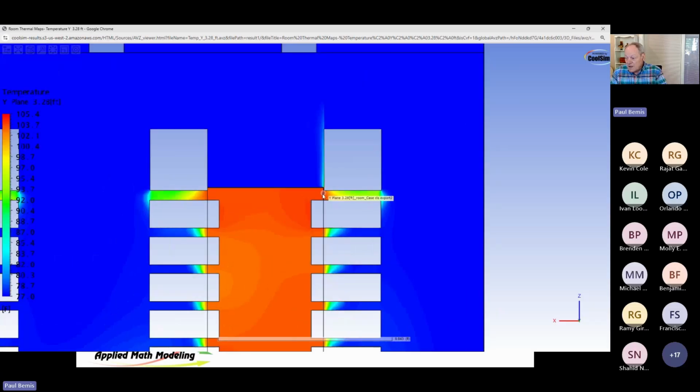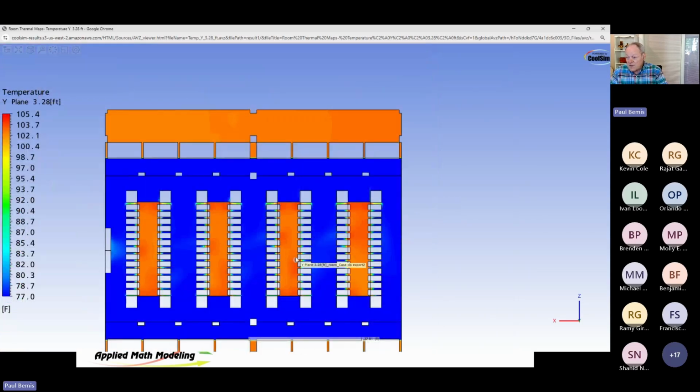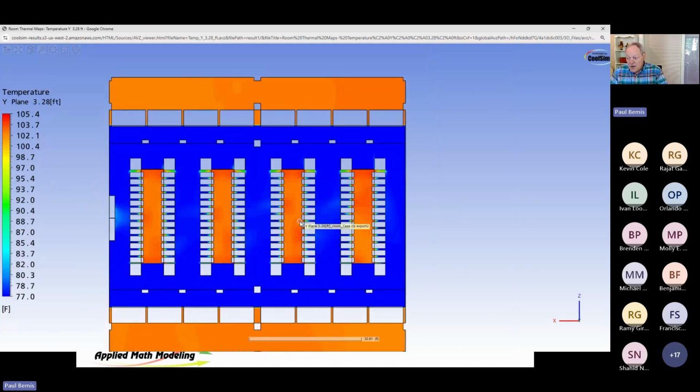Okay, look at it. It's pulling the air out through this leakage membrane because the pressure out here is lower than the pressure in here. The pressure in here is caused by the racks. They're going to continue to blow. They're going to blow at each other and cause high pressure in the center. That's going to force a delta P pressure, and it's going to start to leak out. And as long as that leakage doesn't get too high, you're okay.